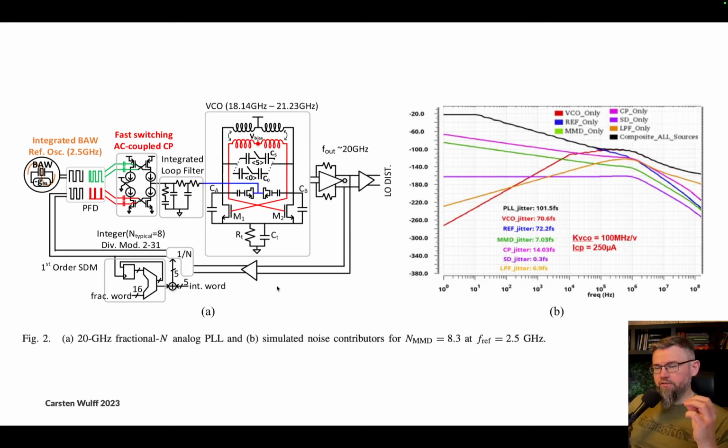And here you can see the sigma delta feedback divider, where you have the fractional word that you want, and then there is a sigma delta modulator. This is first order. But you can actually generate frequencies that are not an integer relationship to your input frequency.